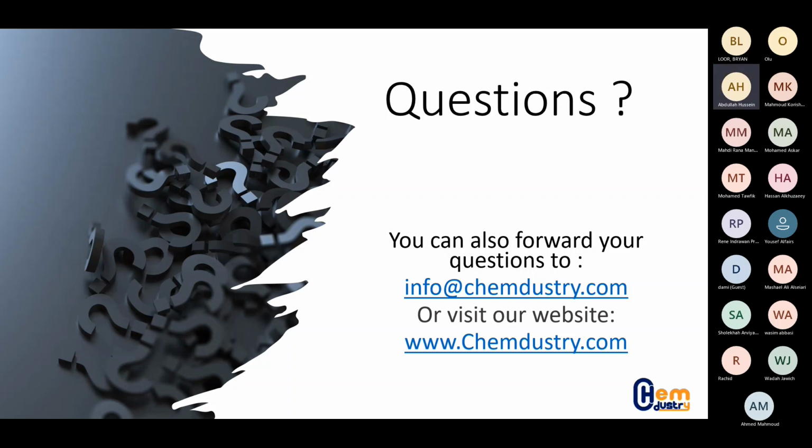After using HCl and G. Okay, you cannot know for sure if it's corrosive to your system or not until you do some monitoring to your system. So before you apply your treatment, you have to do some lab work, usually using a coupon or something, and see your corrosion rate. So that's the first thing you will do. And of course, if using HCl, you will add some corrosion inhibitor there just to make sure your system is not going to collapse, right?